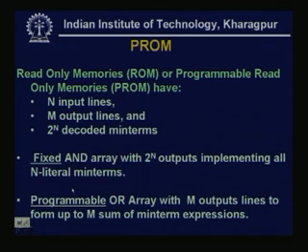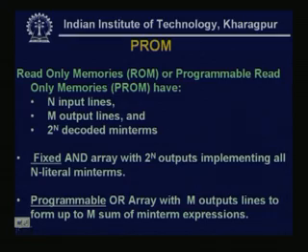Now, we start that. So, if I summarize what we have read so far, the different configurations of the PLD are: the programmable ROM, PROM; programmable array logic, PAL; programmable logic array, PLA; complex programmable logic device, CPLD; and the field programmable gate array, FPGA. Now, we will start discussing in detail the actual architecture of all these PLDs. So, first we see the programmable ROM, the first one.